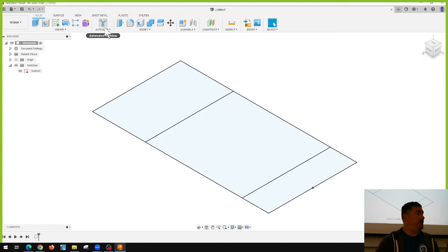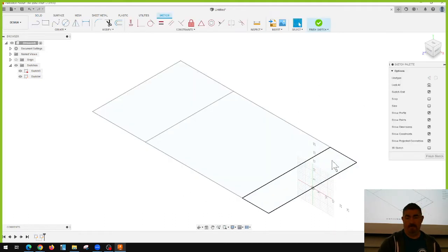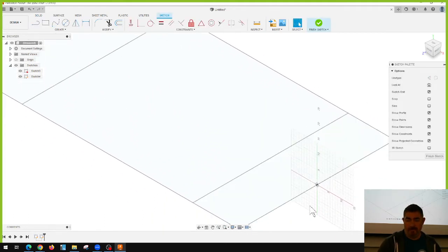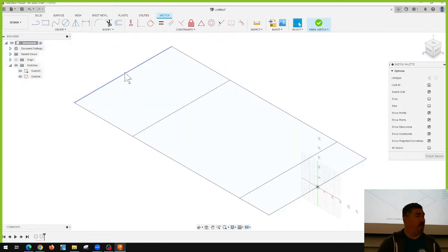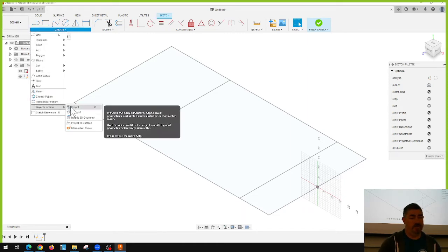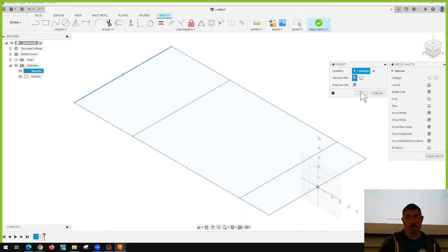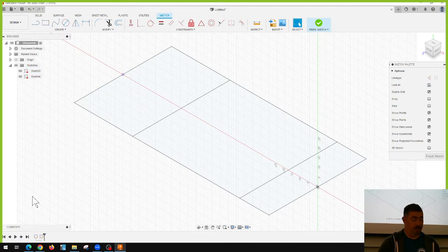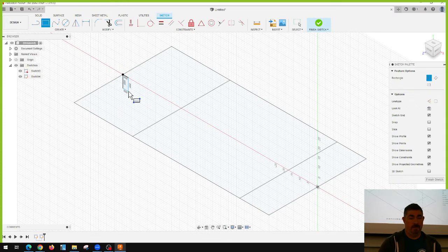So I need to create my C-channel, right? So I'm going to create a sketch here, and I'm going to go ahead and make it on this plane. So I want to make one of the channels going across. And I have a nice origin there I can work off. But let's say I wanted to do this one back here first for some reason, how would I make this line show up on my current sketch plane? Project it. So I go to create, project, I just pick that. Now I've got a point there. And now I can just do a rectangle like that, right?